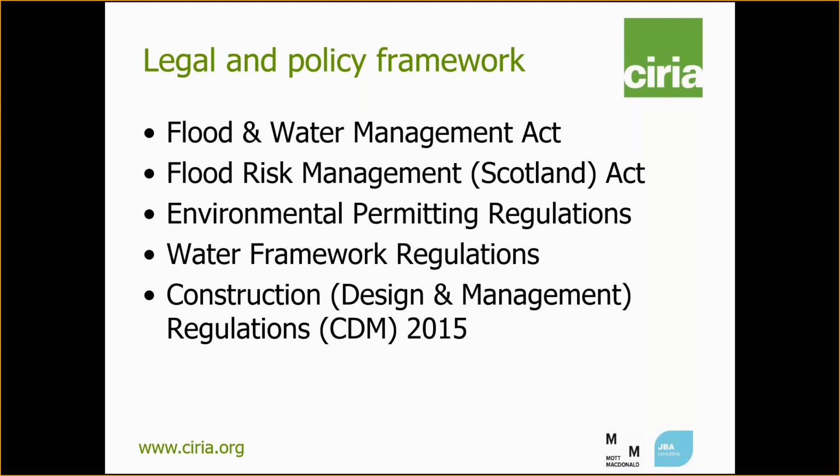We also saw the introduction of the environmental permitting regulations, which introduce environmental permits for works on main rivers, which replaces the flood defence consents in England and Wales. And Wales also introduced requirements for sustainable drainage for new developments. The WFD regulations transpose the EU Water Framework Directive into UK law and set out environmental objectives for water bodies. And finally, the construction design and management regulations replace the 2007 regulations and introduce the principal designer.